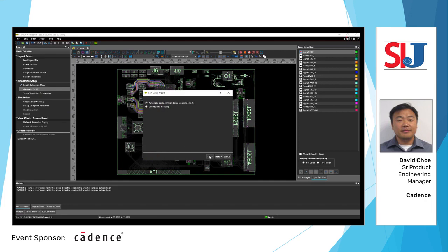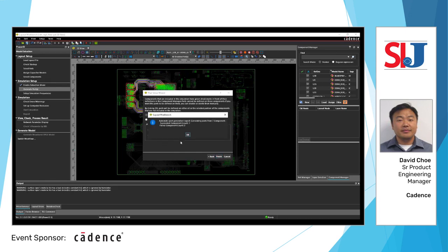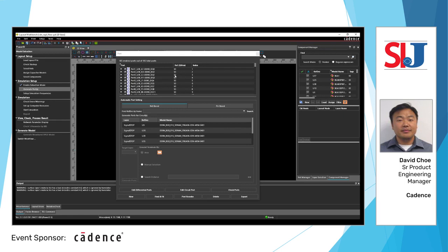And in this case, we're just going to go quickly through this wizard to show you how easy it is to create ports. A lot of people do like to change the power net port impedance down to something low. So in this case, we'll just pick 1. And you can change this in the defaults, of course, if you want to apply it all the time in that fashion. Now, this gives me the message that it succeeded in creating ports at 7 components, and you can see them in the background there. But here's the list of all the ports, and I'll move this in just a second. And we just created 185 ports with just a few mouse clicks.